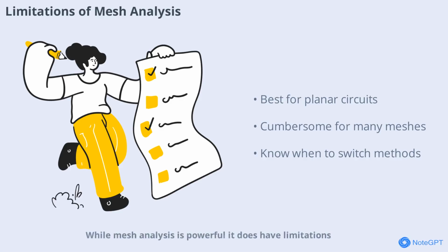While mesh analysis is powerful, it does have limitations. It's best suited for planar circuits and can become cumbersome for circuits with many meshes or non-planar layouts. In such cases, nodal analysis or computer-aided methods might be more efficient. Understanding these limitations helps you choose the right tool for the job.